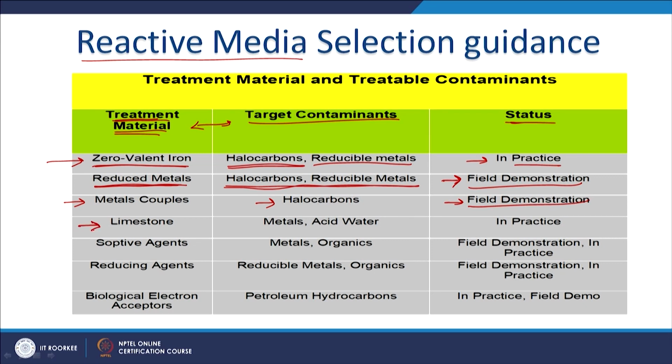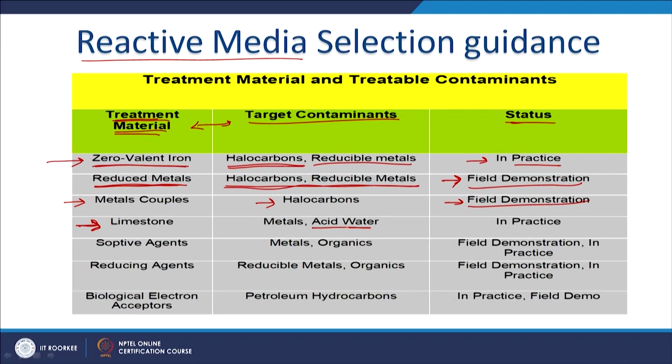Limestone, right? And this is an obvious case. When are we going to use limestone? Obviously when we want to neutralize the water, right? A good case is when you have acid water or acid mine drainage, and one of the aspects you need to control is the pH. So limestone coming in contact with your acid water is going to help neutralize the relevant plume.